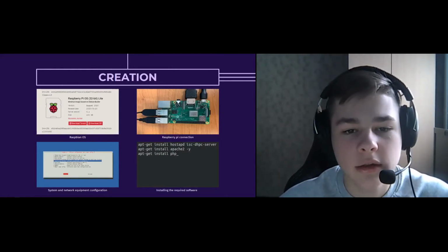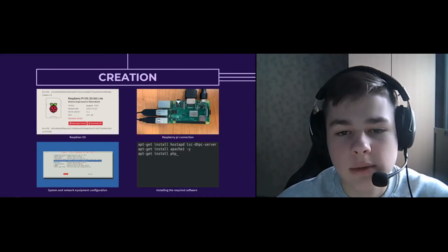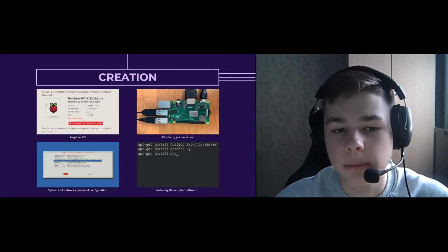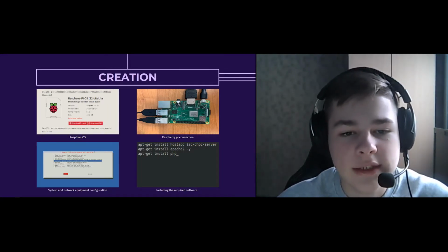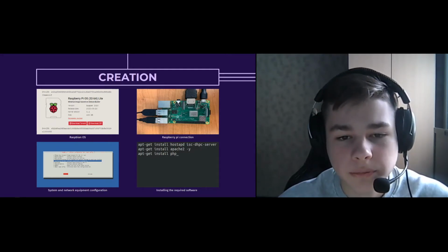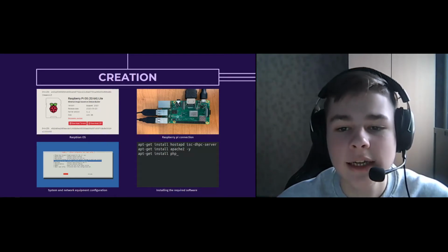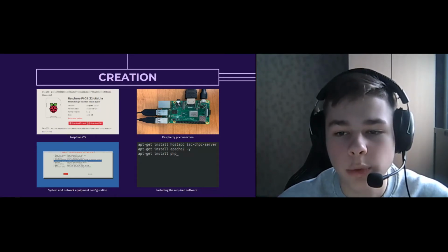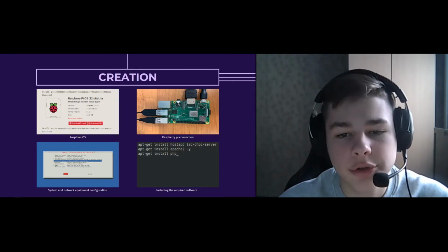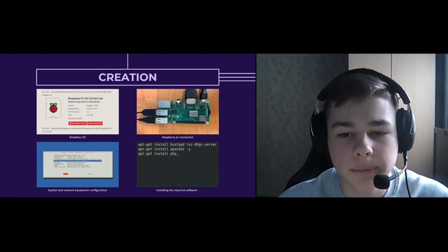To get started, download the Raspbian operating system image on the official manufacturer website and create a bootable microSD card. We install the memory card into the single-board microcomputer Raspberry Pi 3B Plus, connect the monitor to output data and work with the shell via the digital HDMI port, Ethernet cable, and power supply via micro USB.